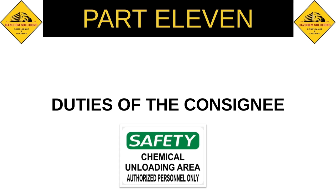Now, vehicles carrying dangerous goods shall be under constant supervision if they are stopped or parked. Opening of packages or unloading for any reason is not permitted except in authorized and properly equipped areas under supervision of a qualified person. And remember, the operator must be informed or notified. Remember to put your triangles, they must be placed on the road, and the operator, again, must be informed. And as a driver, again, remember your tech card. You must follow any instructions on the tech card relating to the dangerous goods if an incident occurs.